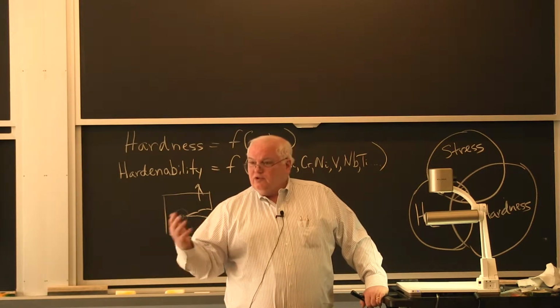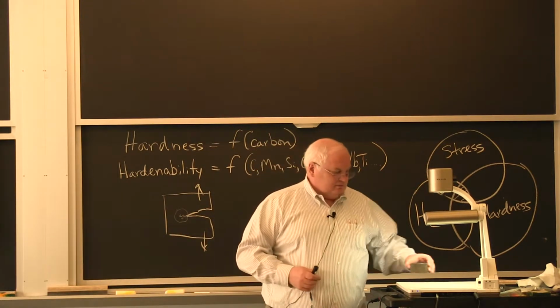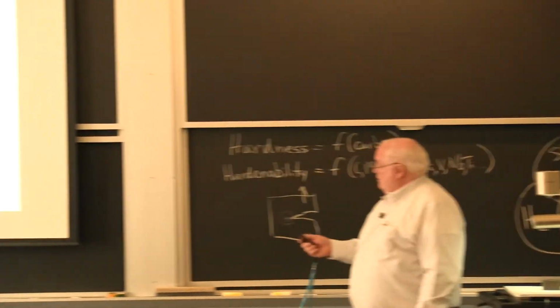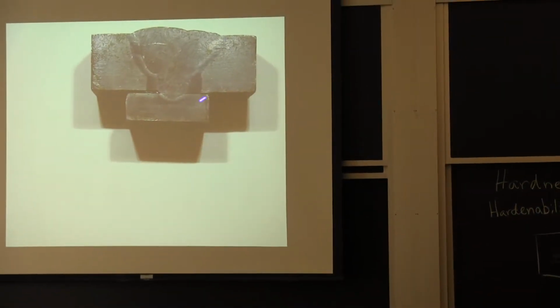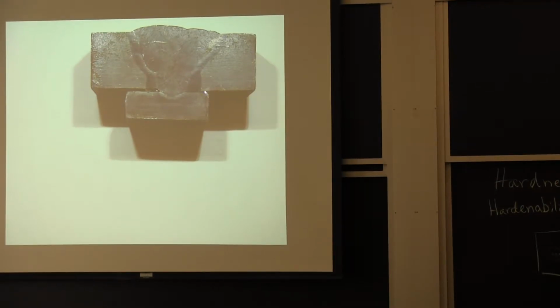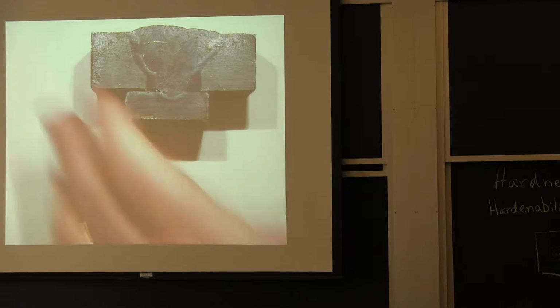The U.S. Navy building nuclear submarines, that's HY-80. That's a weld that's about 1 inch thick. It's got a backing bar so the metal doesn't slip through. It's got a heat affected zone. This thing was probably made back in the 1980s, okay, but I coated it so it wouldn't rust. But basically, the cracks would form in the heat affected zone if you didn't do something about it.